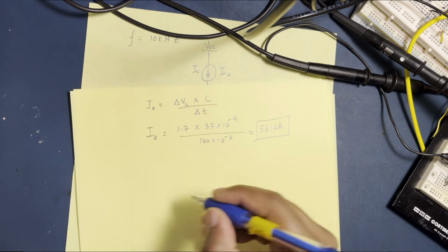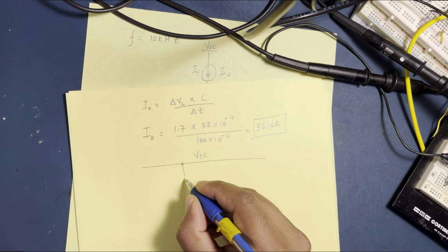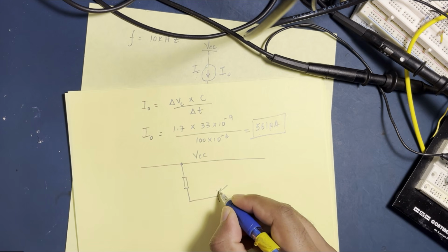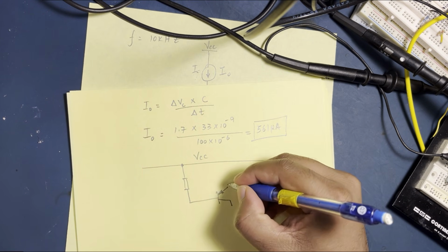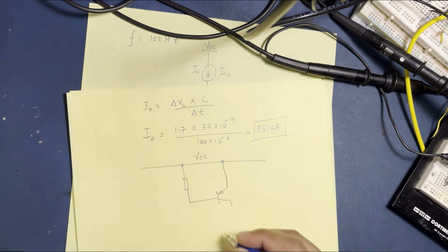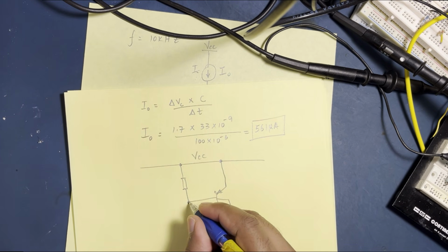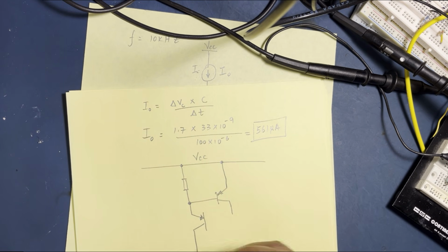Now the current source is basically you have VCC here and we got a resistor here. That resistor is connected to a reference voltage that's going to give it a VBE across it through this PNP transistor. And now that PNP transistor is buffered through another PNP transistor, like so. And now the output is here, right? That's what we designed, IO.